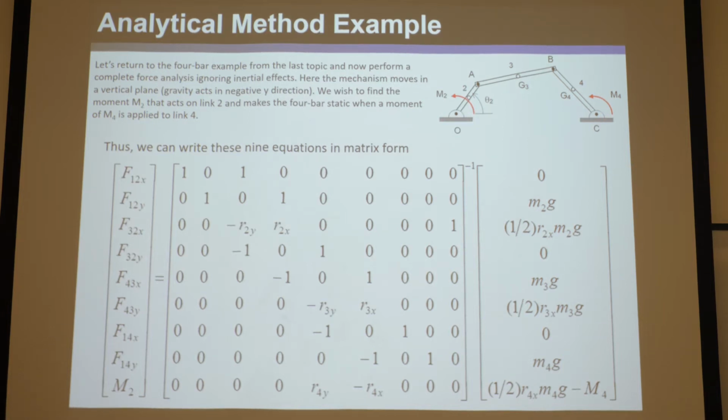I'm not going to make you take the inverse of any matrix that's greater than 2 by 2 on an exam, but if you did this in MATLAB, which you do in the real world, or some matrix calculator, this is no problem for MATLAB to do. Okay, so you do the inverse, times it by that, and you find all these things. Now, remember from the power equation, you could only find M2. But not only do we find M2, but we also find all the forces that occur at the joints.